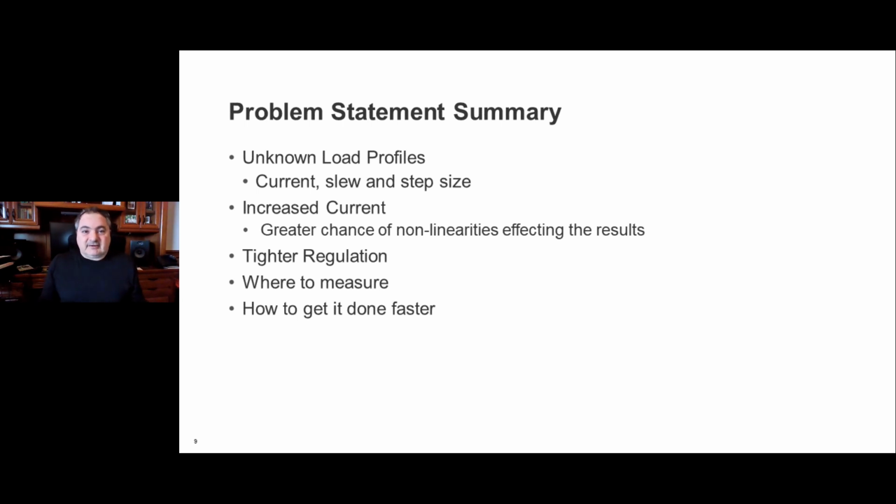So the phases on the outside, if you're looking down on the board from the left and the right-hand side, are at different lengths than the ones in the middle. So they probably have different trace inductance, power plane inductance, and series resistance associated with them. So they're going to, by definition, have different thresholds for when they need to be activated and not activated. You think about these solutions, as you add a phase or remove a phase, when the current goes up and down, these phases are shared on.